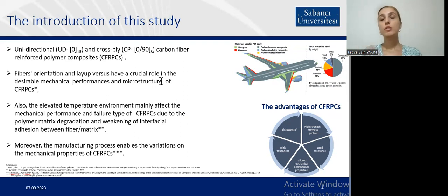In traditional defense and aerospace applications, autoclave curing is mainly used for low void content and high fiber volume formation, because autoclave curing applies high pressure and high temperature, giving less void content and a high fiber volume fraction.